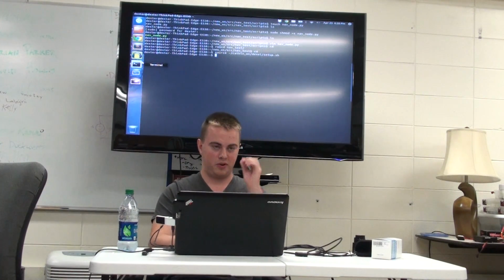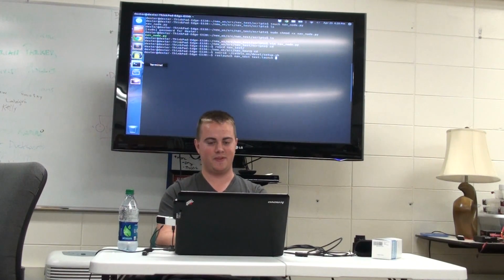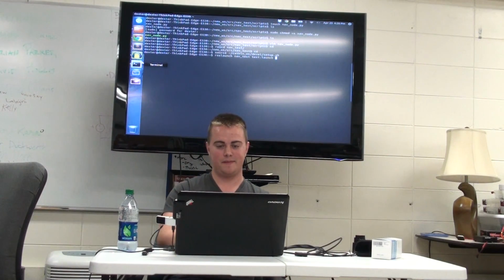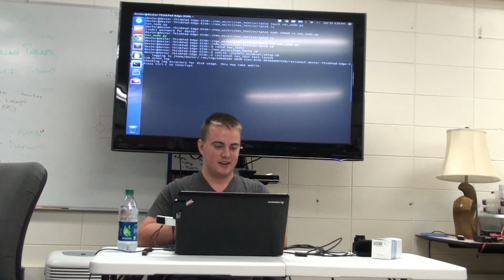Okay, and then I'm going to use ROS launch. So I'm going to say ROS launch, again, package name, and then the launch file. If you only have one, you can just press tab and it'll autofill it in because there's only one possibility. So I call it test.launch, and then I'm going to hit enter. And so it's starting up ROS core for me. It's taking a second.